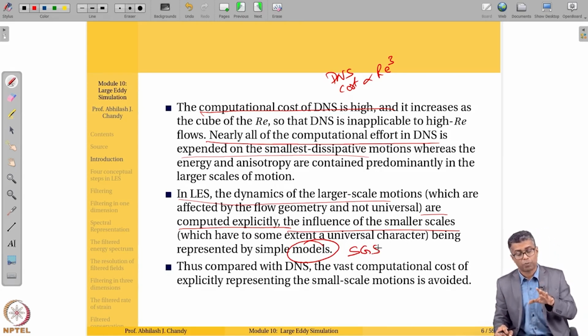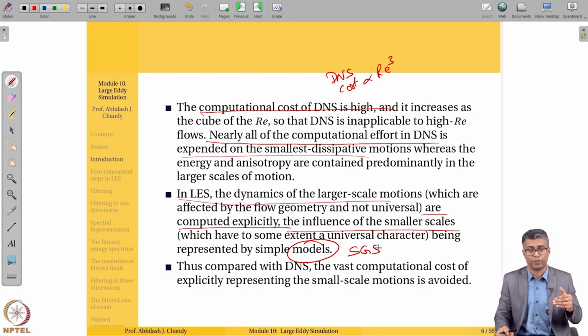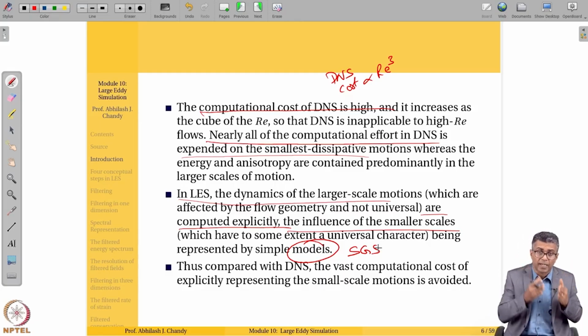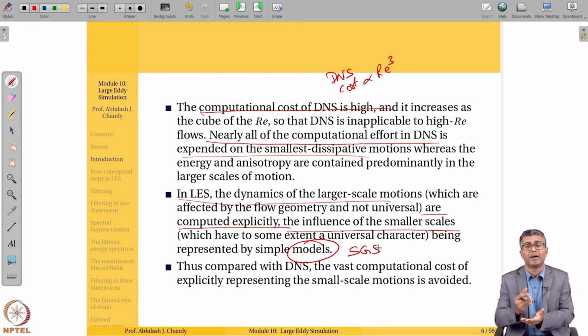In the RANS approach, we actually went through this exercise, isn't it? We took the Navier-Stokes equations, did a Reynolds decomposition, and then time averaged it in order to get the Reynolds equation. Then we saw some new terms popping out, the Reynolds stress term, which we needed a RANS type approach to close. Here too, when you filter your equations, new terms come up, which are called the residual terms, and you will need approximations for those.